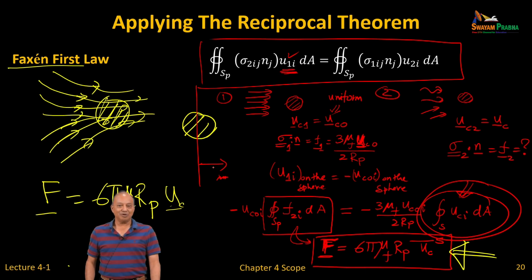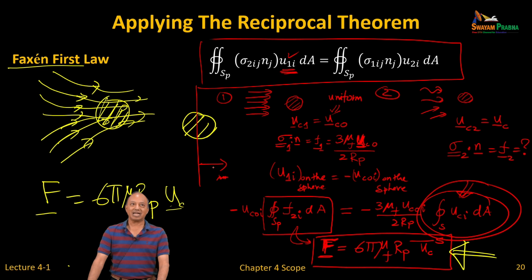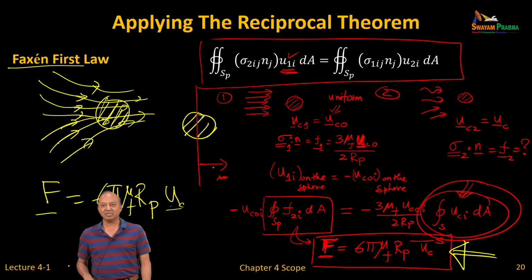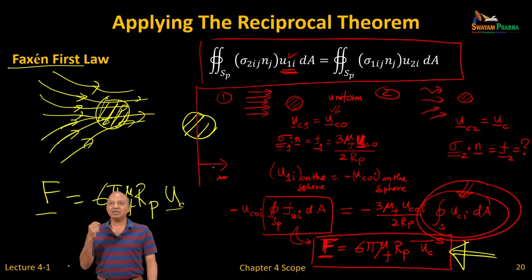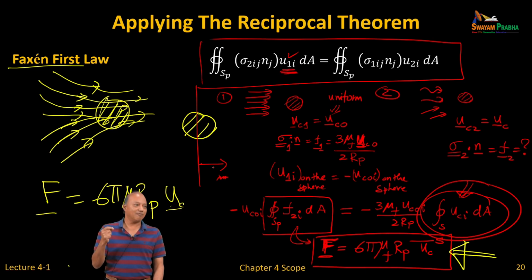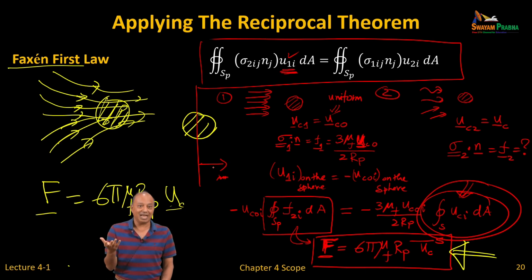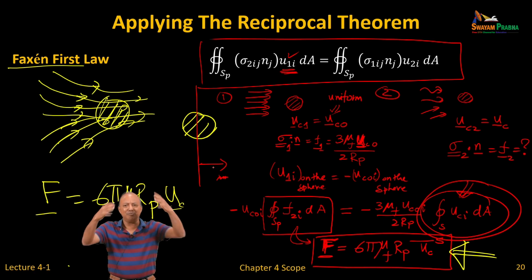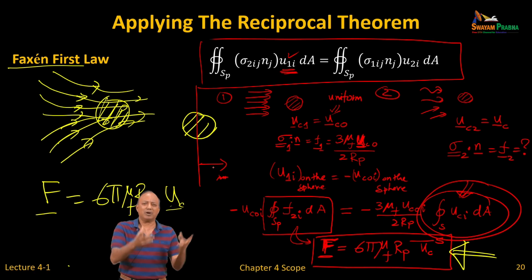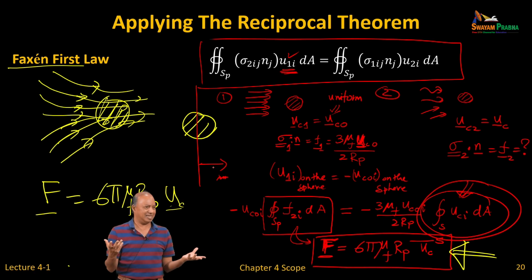So in other words, when you think in terms of Stokes drag, and lots of drag relations that we use, keep in mind that we are talking about the undisturbed flow seen by the particle, and that could change on the scale of the particle. If the particle is small compared to the turbulent scales, then who cares? The whole particle stays at the same velocity.